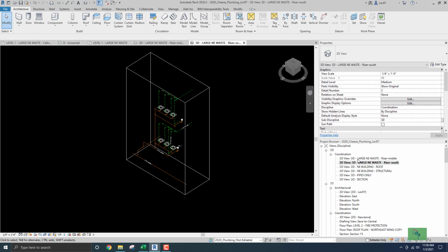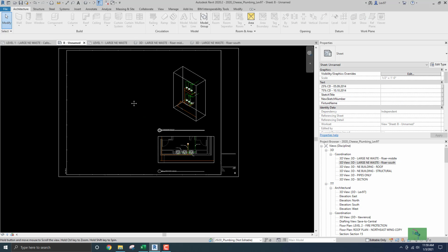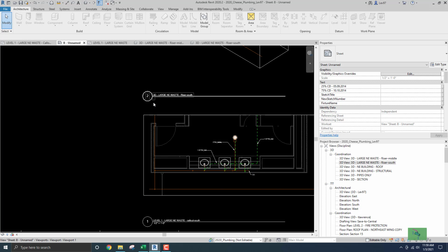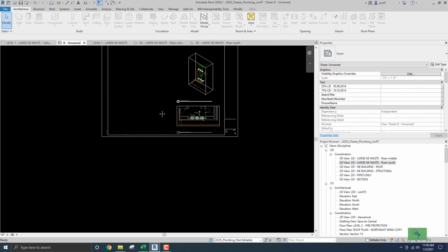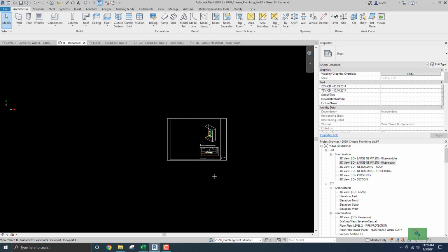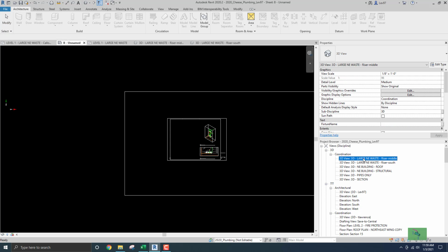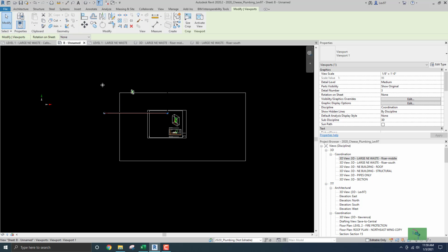Okay, let's go here again, and let's go to the sheet. So 1/2, 1/4. Oh, there's no scale on the riser. So I'm gonna drag the middle onto the sheet. I'll left click and just drag it over, and it's there. And I can hold shift and use my arrow keys to go down just to position.